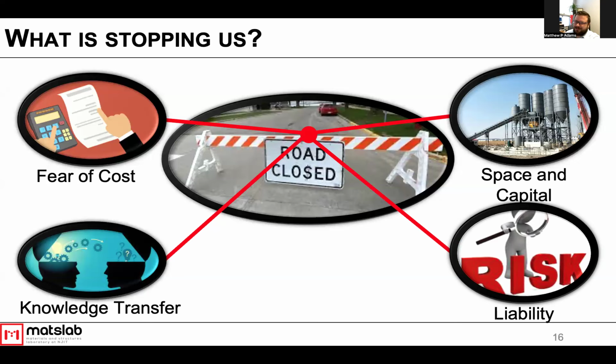The positive thing is that with most of our low carbon concrete tools, we're not looking at major structural failure, sudden collapse issues. We're really looking at durability and serviceability issues that can reduce the long-term performance. That's still important, but we're not really concerned too much right now about sudden collapse. However, that liability is still an important question.